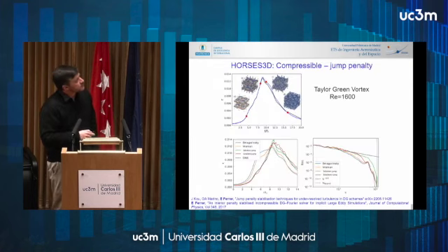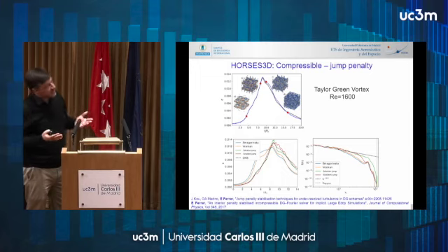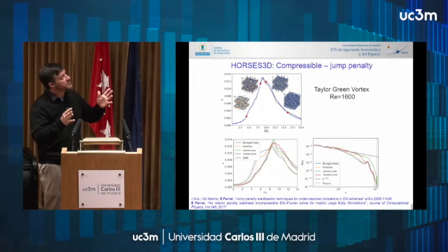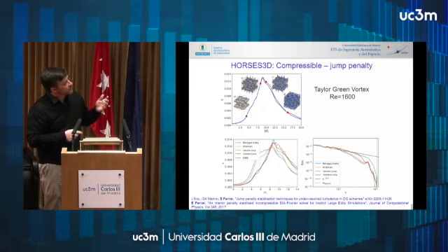And what we see is that when compared to Smagorinsky or Vreman models, these are classic LES models. So this is the Taylor-Green vortex, so I should explain what that is, sorry. So this is an academic test case that we like because you start with some blobs in your solution, periodic boundary conditions, and then turbulence starts to develop. We have some transitional flow, and then an isotropic decay of turbulence eventually at the end. So what we see is that when we compare our solution, jump, gradient jumps, to the classic Smagorinsky or Vreman models, we get much better solutions.